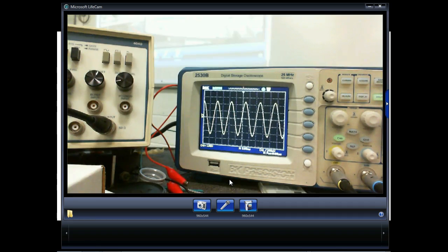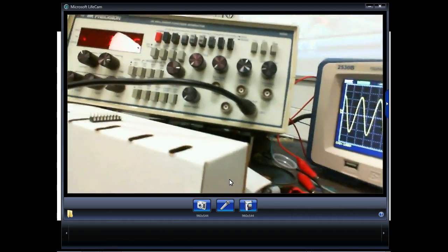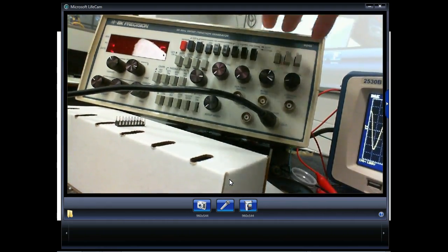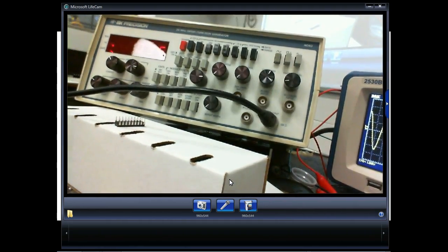Well, how does it get 120 volts AC? Well, it does it electronically, right? You understand? There's an inverter in there that electronically takes DC and reconverts it back into what? AC. So what's nice about this guy, this is a function generator, and its function in life is to generate signals. It takes AC, converts it to DC, and then we can generate different types of signals with it. So this is not Alabama Power, this guy's doing it electronically.